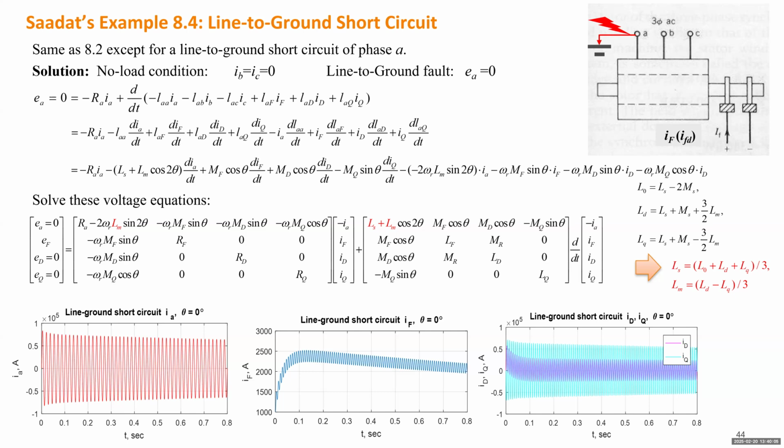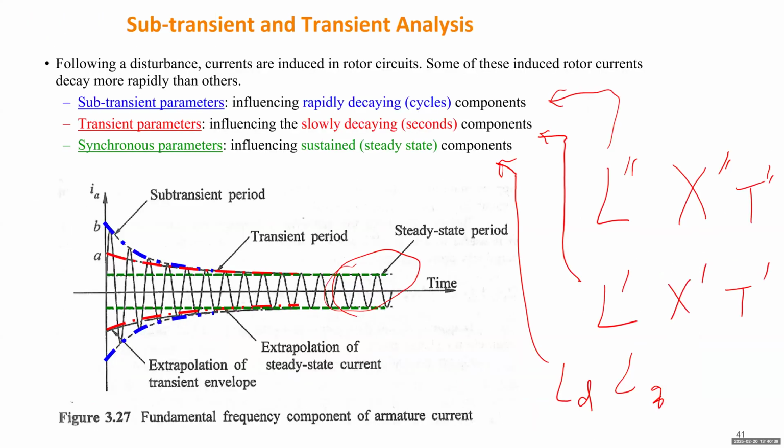Using our first model, we can accurately study any dynamics of the system, no matter whether it's a balanced fault or an unbalanced fault. But the problem is that it's not very convenient. We don't want to integrate so many equations every time, no matter what dynamic we want to study. Then we need to think about how we can simplify the model. It will be very beneficial to categorize 3 types of dynamics, and come up with parameters categorizing each type of dynamic.